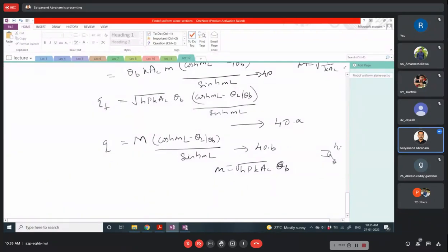We don't have to worry about that, because once some temperature or heat transfer or boundary condition is given, this is what we can say. If the outer condition is given and it is expressly said that heat transfer is also happening from the tip, then you can consider the tip. Unless it is explicitly said, you don't have to worry about that. Very good observation.